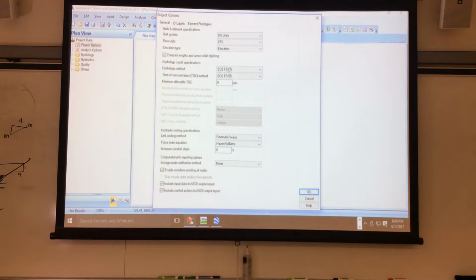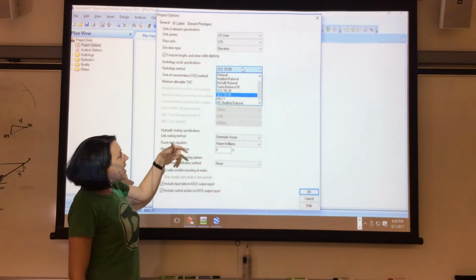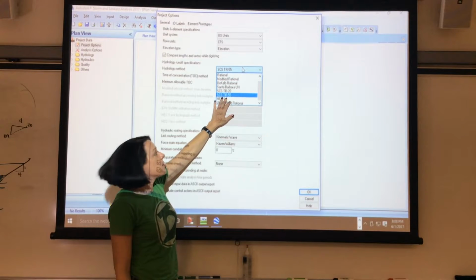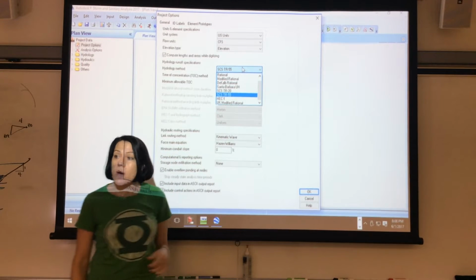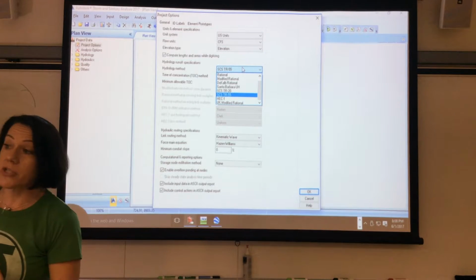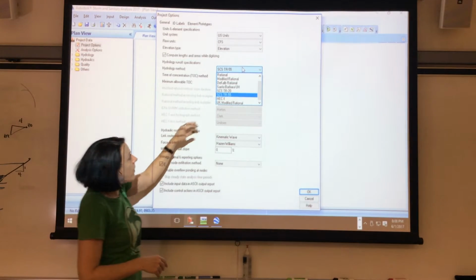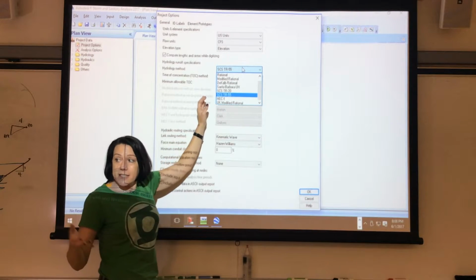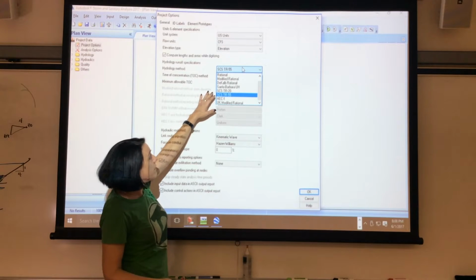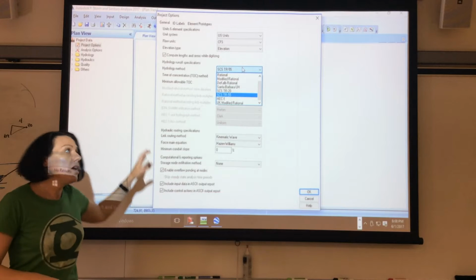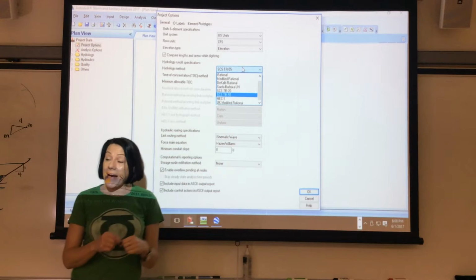The hydrology runoff specifications, these are the different methods. In this class, we've gone over the SCS TR55, which is the NRCS TR55. The TR20 is similar to the TR55, but for larger scale projects, typically think that way. Santa Barbara unit hydrograph, that's just another method, instead of the SCS unit hydrograph, of how to do the inflow-outflow hydrographs.